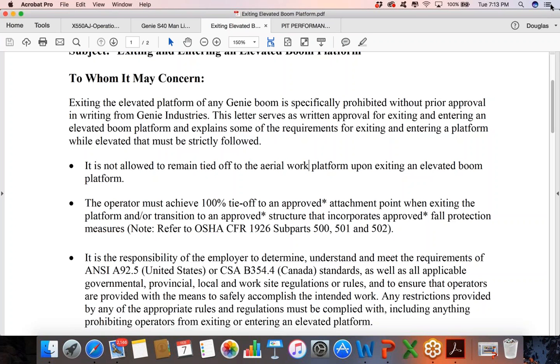In addition to that, it could be hearing damage from continuous noise exposure, or burns and eye damage from welding, cutting, or chipping. So flash burn, basically. Also, sprains and strains from improper lifting or from carrying objects improperly, using improper methods or maybe excessive weight. Electrical shock from poorly grounded and defective tools and equipment, especially if we're doing some type of arc welding, electrical welding. Injuries due to defective tools or equipment, and injuries due to improper tools or equipment or the way that we're using them. It could be a faulty tool, a damaged tool, or even improper tool selection.